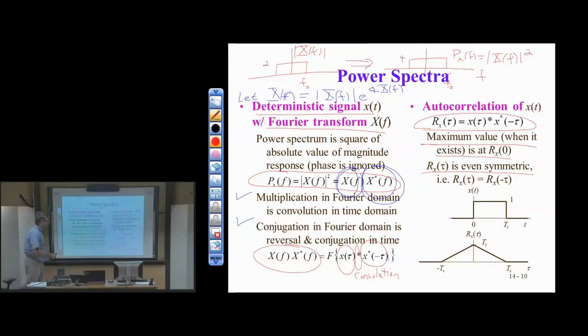Correct. So the key is that this is the autocorrelation. The next step is cross correlation, which is what we'll ultimately do. The matched filter does autocorrelation, or rather, we'll get the matched filter from the autocorrelation function. In practice, that matched filter is cross-correlating against the received signal, looking for the pulse, like you did looking for a header in a sequence of received values in homework 4.